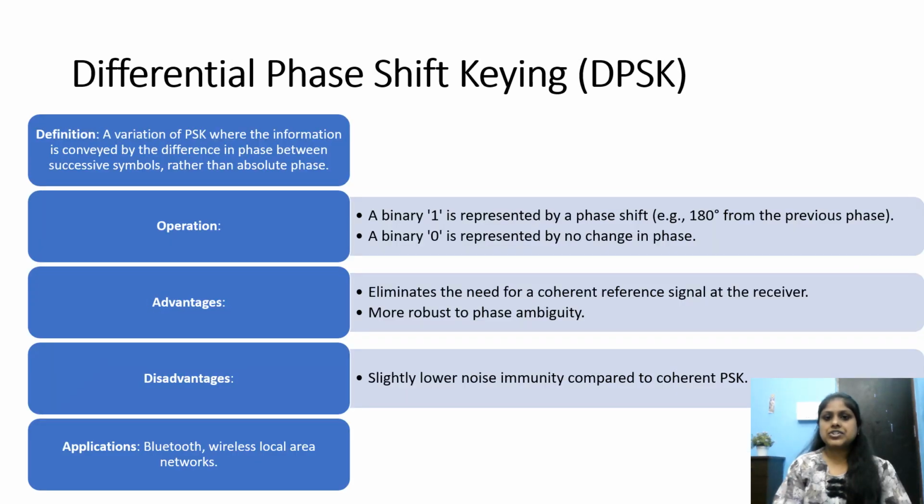Differential phase shift keying, DPSK. A variation of PSK where the information is conveyed by the difference in phase between successive symbols rather than absolute phase. And the operation includes: binary 1 is represented by a phase shift and binary 0 is represented by no change in phase.